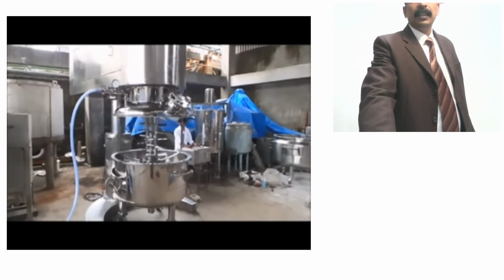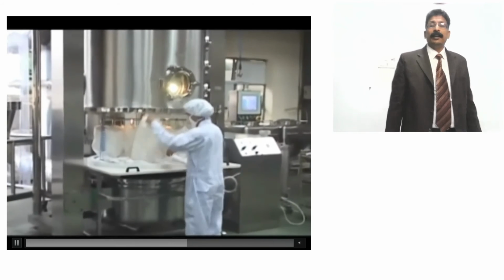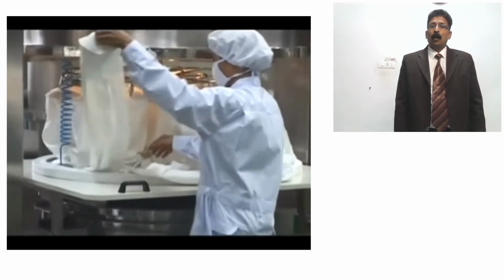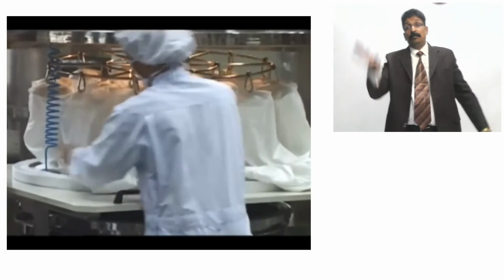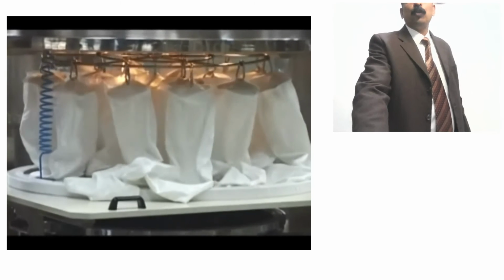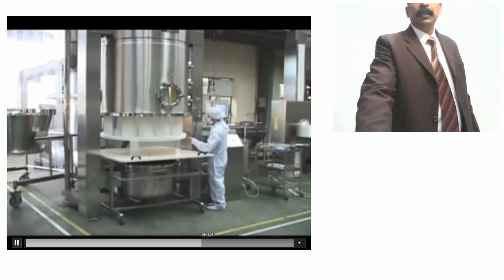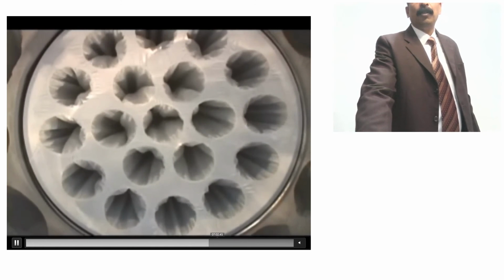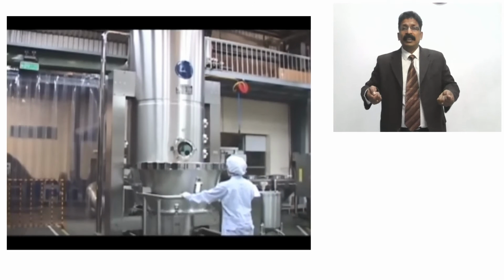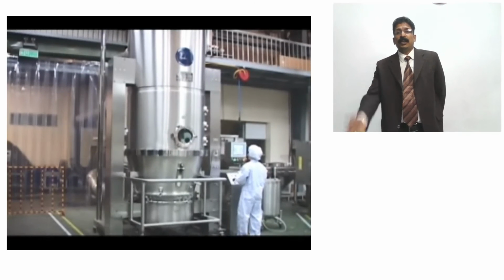Then you can see the place where the bags collect the fines in the fluidized bed dryer as they dry. These bags collect the fines thrown up by the hot air blown through from the bottom for drying, and this is how it works automatically. After fixing everything, you can see the top of the fines collecting bags, and he brings that vessel and fixes it to the fluidized bed dryer, then switches on so that it starts drying.